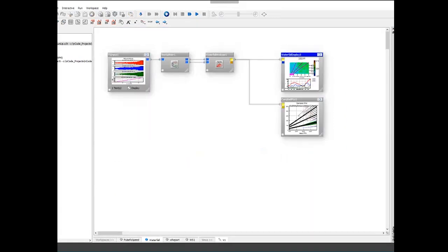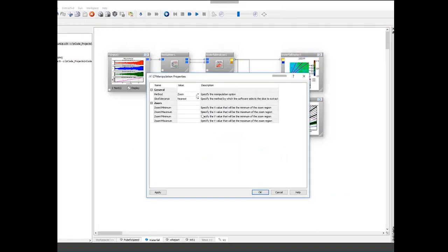So what we have, if I go in the rotating machinery palette, is this complex frequency manipulation glyph. Let me drag this one in, connect it like that and double click on it. You've got several options here. What I want to do is extract an order slice, say order number 2.